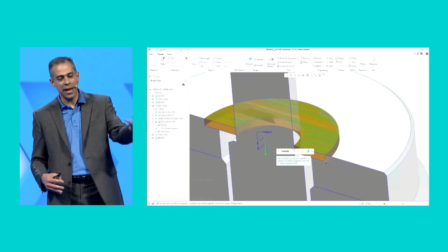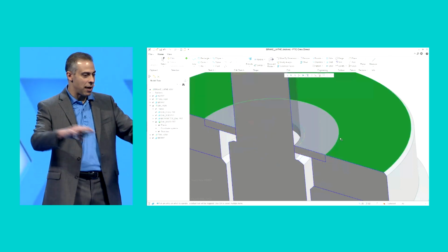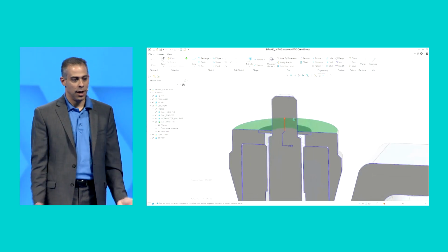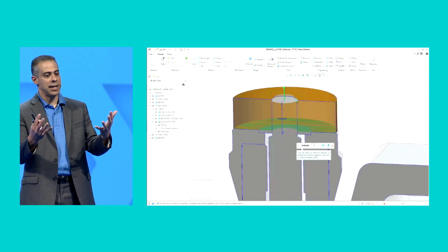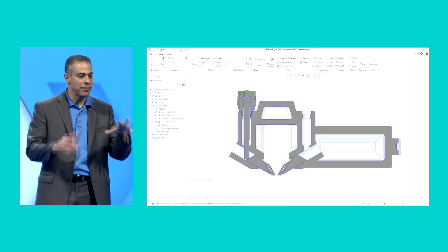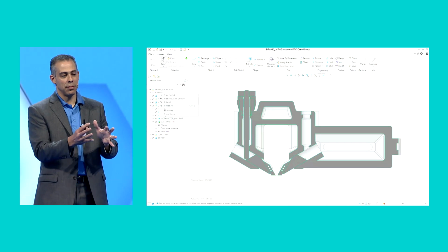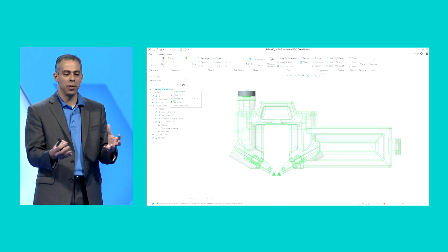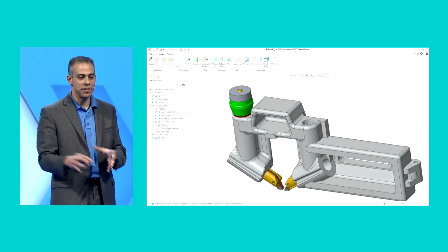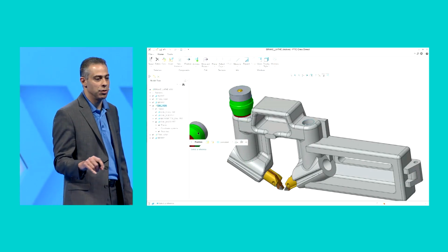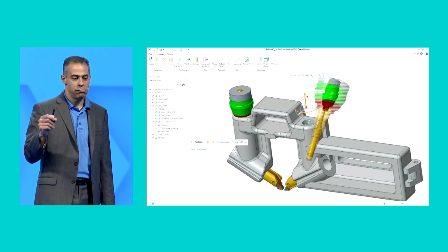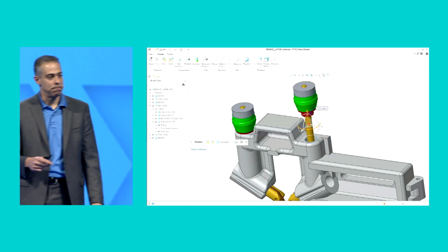So you see, I've made this new component. I'm using some surrounding geometry from the parts around me to create 2D elements that I can then extrude up to create 3D elements. This is all new geometry in my part. And now that I've got this added sub-assembly with this new part in it, we have this nice capability called shared occurrence where I can repeat an existing component in my assembly. It's very, very simple. It's right there on the right mouse button in Creo Direct. And now I have it right there on the pointer, and I can assemble that in, okay?